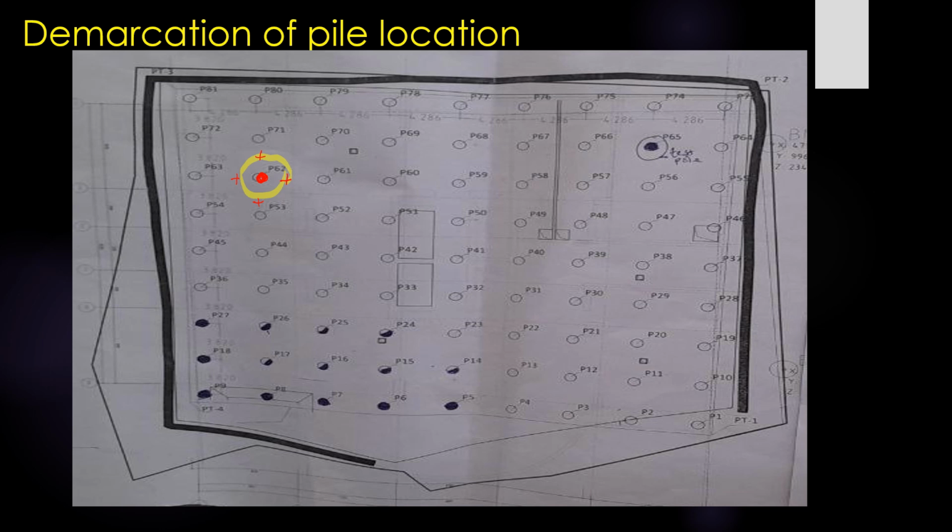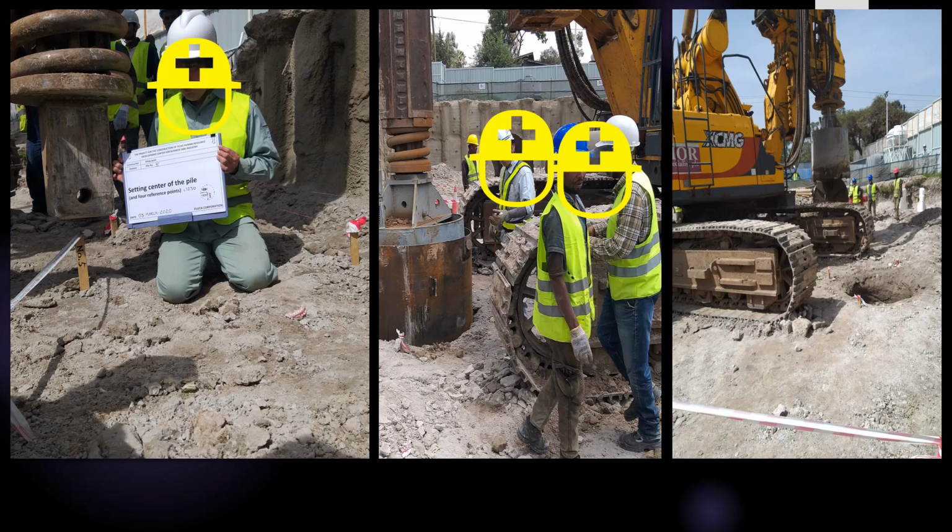The next thing we need is reference points, which are established at least 2 meters from the pile center, drawn in orthogonal directions like this, like this, like this, so that we have reference points for our pile. This is our pile, which is circled in dark lines.